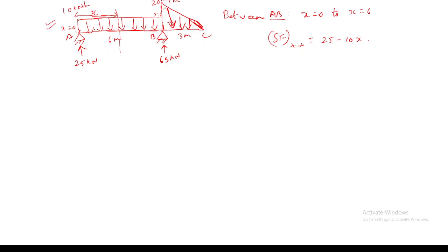So what will be the shear force due to this 25 kilonewtons? Will it be positive or negative? Because it is acting in the clockwise direction when we view it from the left hand side, it is positive. So I have written it as positive 25. Now coming to the uniformly distributed load.